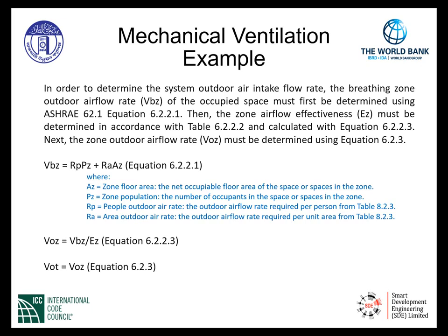We will pick these values from a table, and this is going to be the airflow effectiveness coefficient, if you will, and this will derive a value to modify what we've calculated above, either modify it or keep it the same. In this condition where we apply an airflow effectiveness calculation, we must specify and design for the higher airflow rate. V sub OT is our last equation.